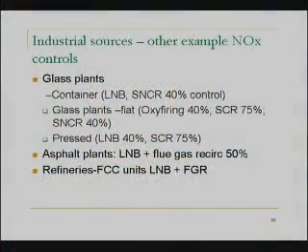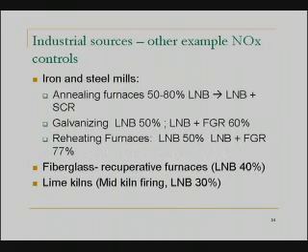There are EPA summaries of the degree of reductions from certain technologies for other types of NOx sources, which generally include combustion controls such as low NOx burners, and downstream controls such as SNCR and SCR. Certainly those types have been applied to a lot of categories such as glass plants, refineries, iron and steel mills, and other source categories.